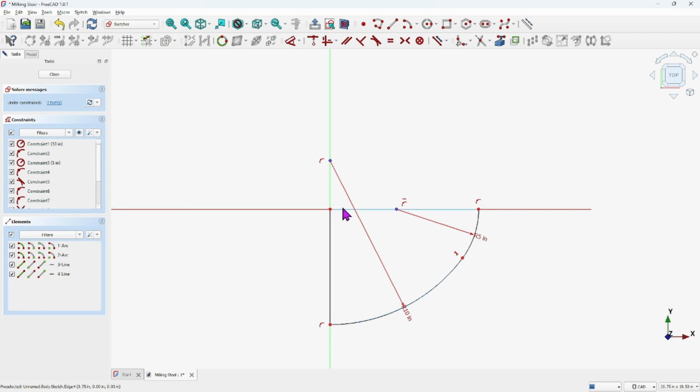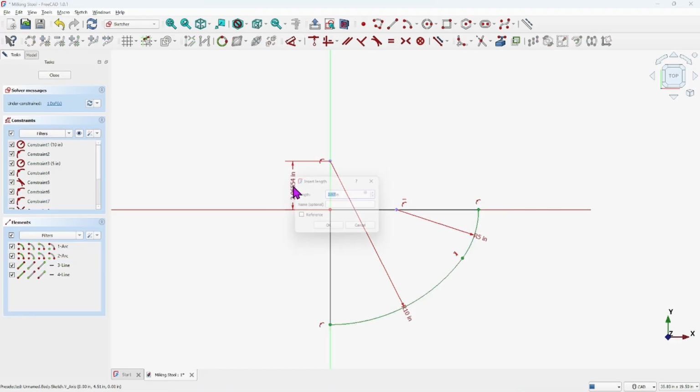So if that's tangent, there's a radius. It seems like this radius point needs a dimension from here to here. Okay, and I'm just going to accept that dimension because by locking all, look at that, it's all starting to fall into place. By locking it together with endpoints on the X and the Y axis, and then performing a constraint here, we use less dimensions.